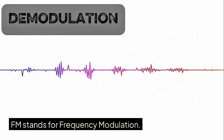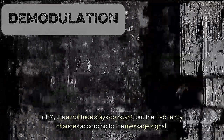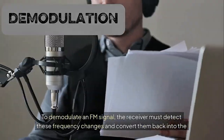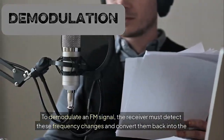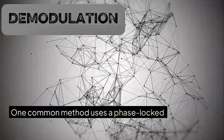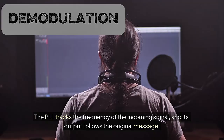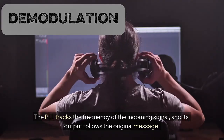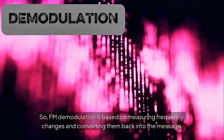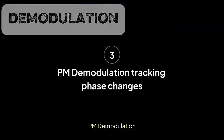FM demodulation. FM stands for frequency modulation. In FM, the amplitude stays constant, but the frequency changes according to the message signal. To demodulate an FM signal, the receiver must detect these frequency changes and convert them back into the message signal. One common method uses a phase-locked loop, or PLL. The PLL tracks the frequency of the incoming signal, and its output follows the original message. So, FM demodulation is based on measuring frequency changes and converting them back into the message signal.